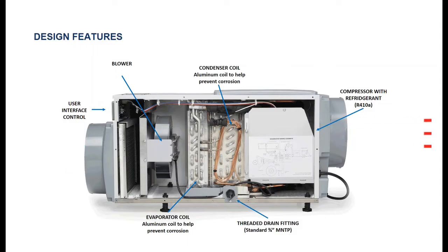It's not going to give us any dehumidification, and so that dehumidifier is going to be forced to run a lot. So just use your standard Manual Js for residential and add in that dehumidifier based on our very simple sizing chart, and you'll get good results. The air conditioner and the dehumidifier will work together.